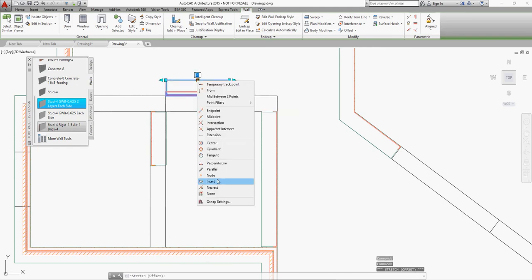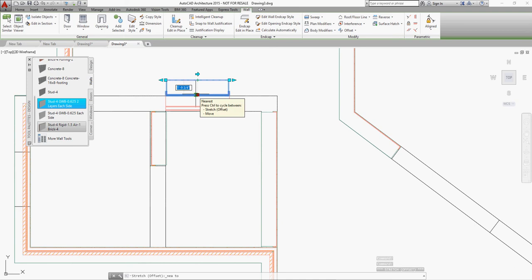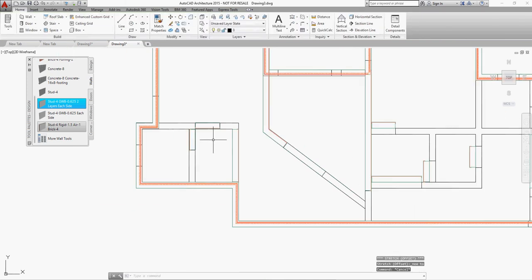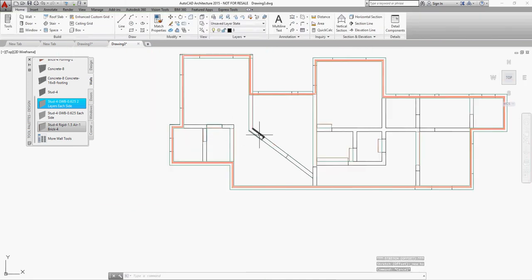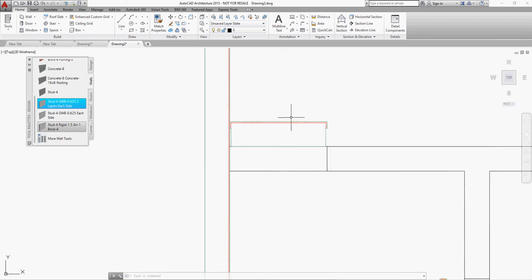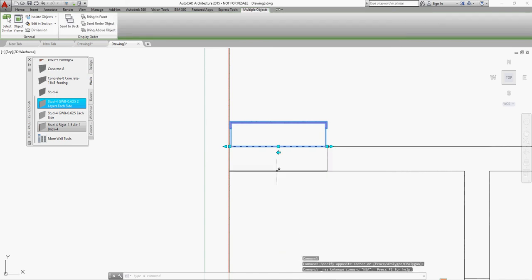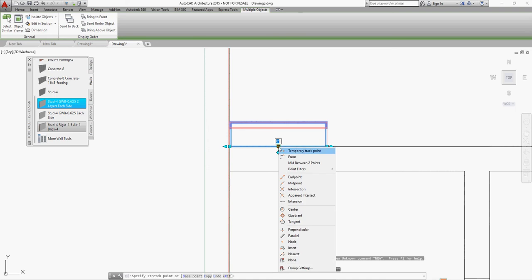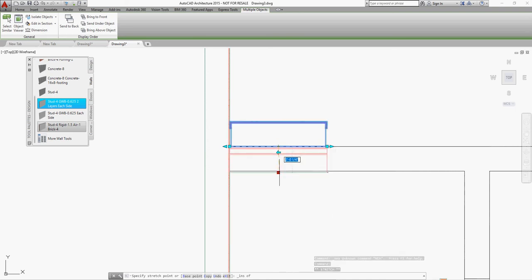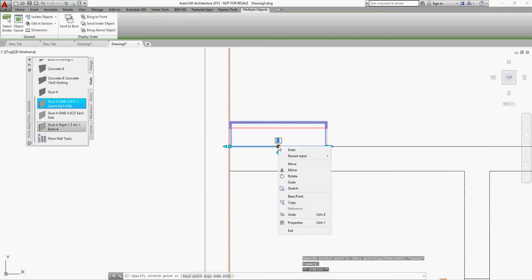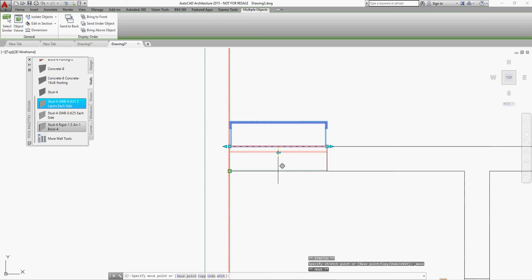Okay. And if you look at these two walls, I'm going to select this wall and that wall. Yeah, that cleaned up. Okay, and just going to double check that those two cleaned up. You can kind of see that there might be some issues there, and you can use the wall cleanup to clean those corners there.